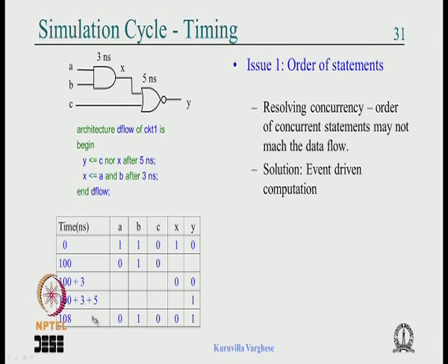You can introduce, say, events on A at 100 nanosecond, 110 nanosecond, 120 nanosecond. You can even think of a scenario where A is changing at 100 nanosecond and also at 102 nanosecond, before even the X changes. Okay. So you think about what really happens, you try to work out such a situation, that will bring clarity to your thinking.